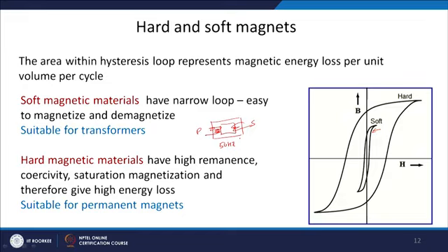That means 50 times it is becoming positive and negative. So, this core material will also get demagnetized, and this whole cycle will be repeated 50 times in a second. 50 hertz means this hysteresis loop is being traversed 50 times in the material. So, in each cycle you are losing certain energy.